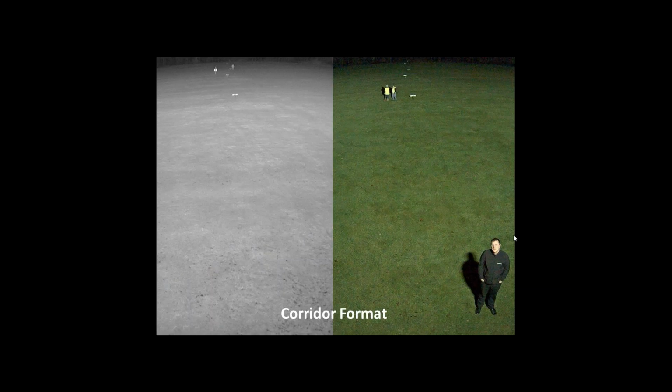Equally, this is an example of an Axis camera feature, corridor format. A lot of the time this will be used internally, but we have tested this externally. So if someone was using this down a narrow field of view, like a perimeter fence line or walkway, pick a narrow angle illuminator that's going to illuminate all the way down the scene, so you can see all the way up into the distance of these images here. We've got an infrared example and a white light example too.